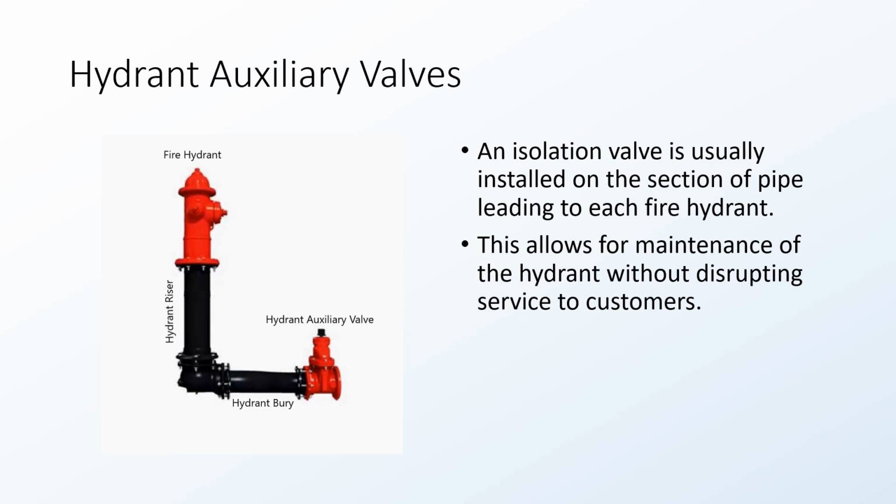In this image that you see off to the left, one thing that is pretty common nowadays is what we call a hydrant check valve. So when these hydrants get hit, there is a check valve there that will close, preventing water from spraying everywhere and creating a bunch of erosion or damage due to that missing fire hydrant.